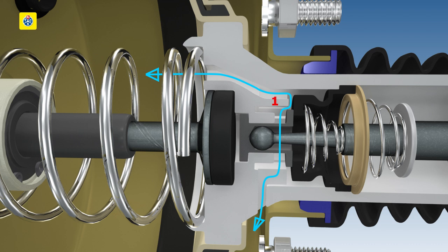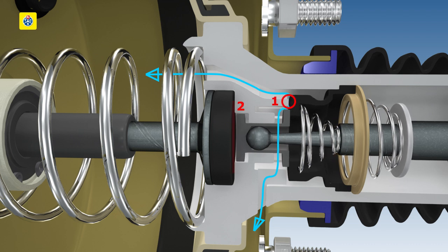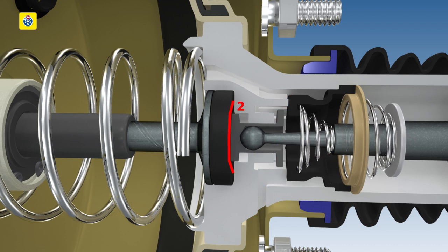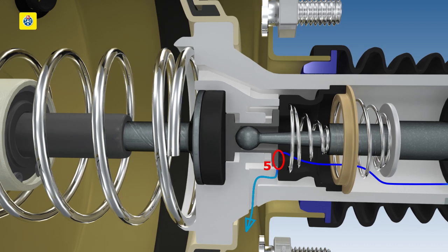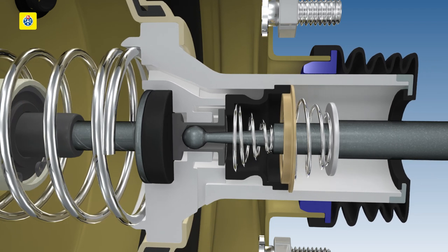Pressing the brake pedal closes the connecting channel and compresses a reaction disc, which opens the passage to atmospheric air. The resulting pressure difference moves the diaphragm piston until the atmospheric air passage is blocked. By increasing the force with which the pedal is depressed, the phenomenon is repeated until maximum differential air pressure is